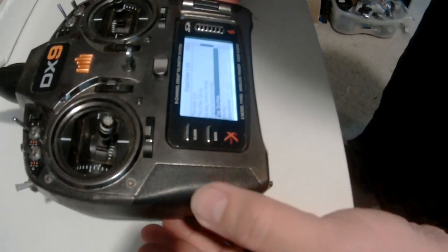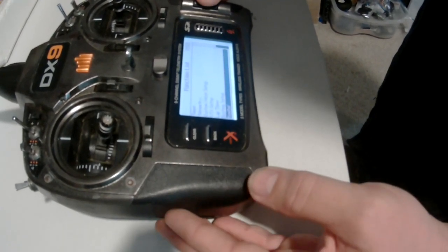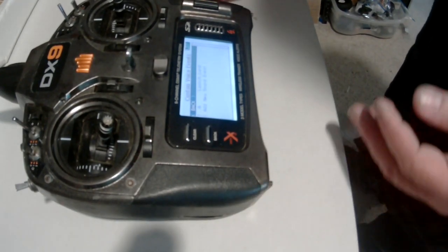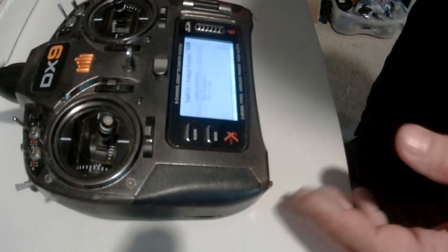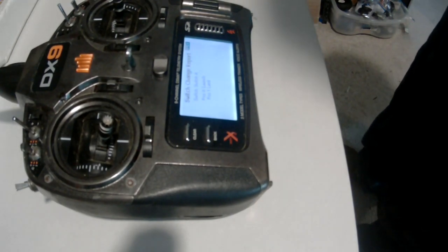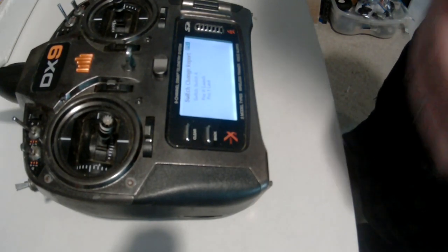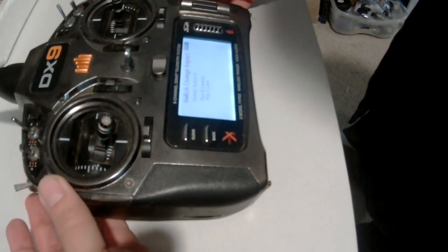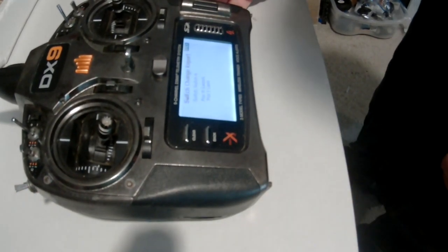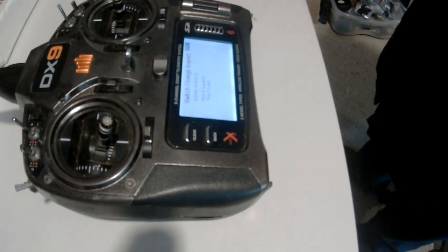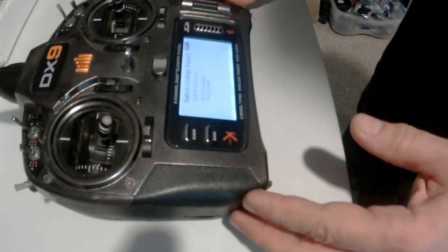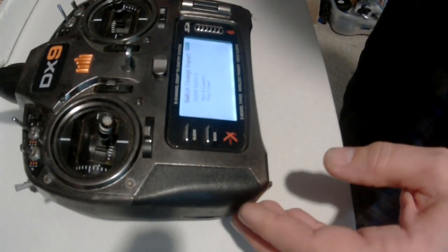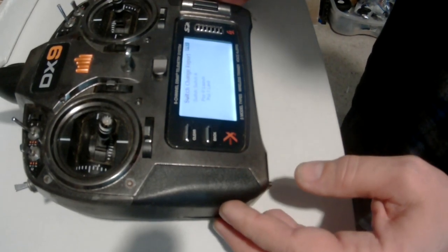Let's see, and then just so it will announce whatever I want. Switch A, I tell it that for the down position, position 0, to announce that it's the launch mode, and then for position 1 to announce that it's the landing mode. So the launch mode, and landing mode. So that's really all it is to this very simple way to use the flaps menu to set up elevator presets for the launch and landing mode.